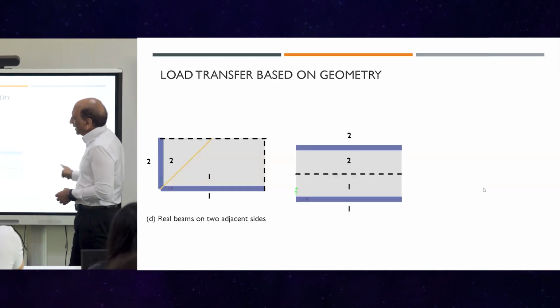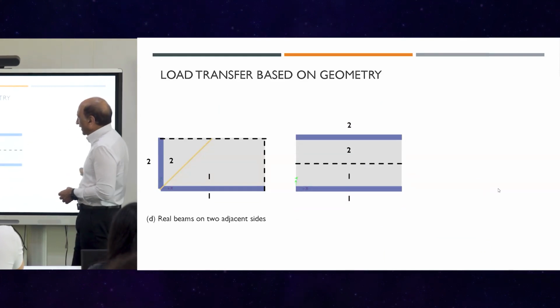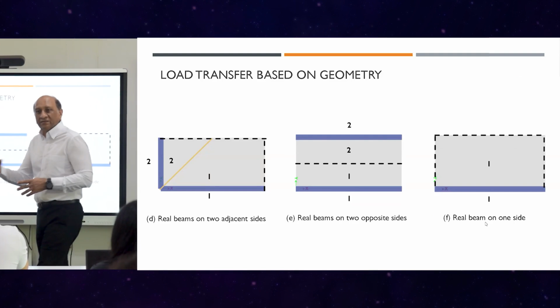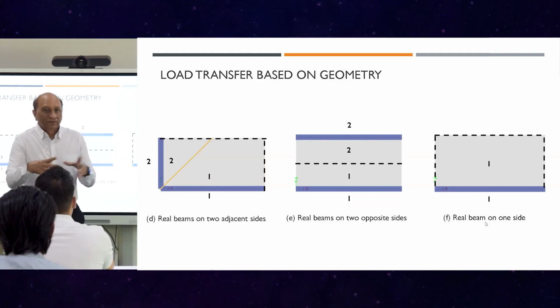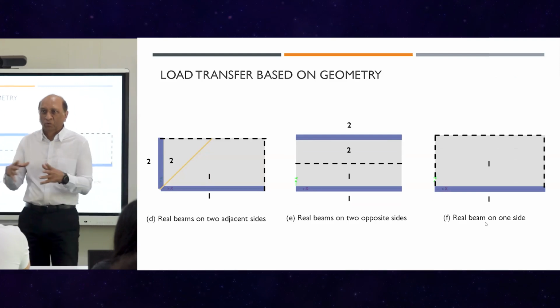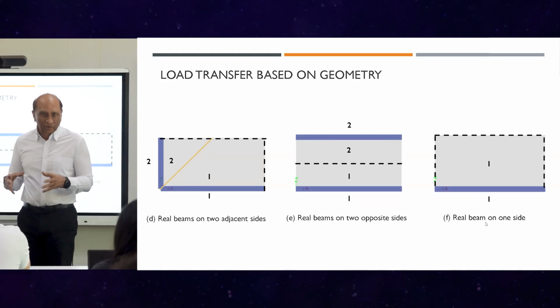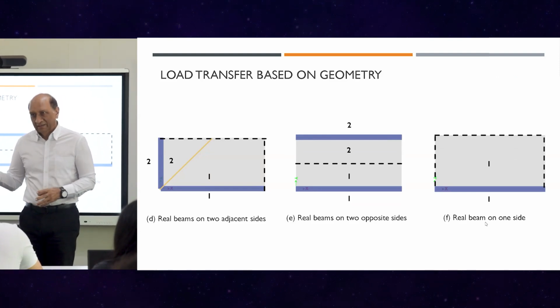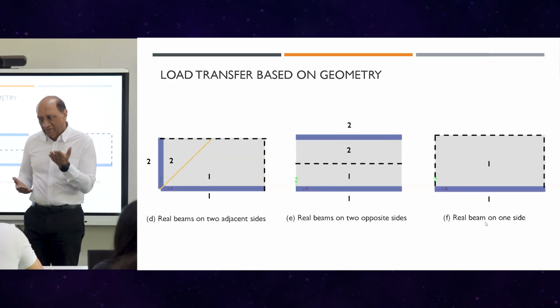So in this one, two walls will go like that, which is probably correct. And one wall, of course, cantilever will go like that. So they created all these hundreds of cases of load transfer mechanism, and it only worked for rectangular or mostly rectangular slabs. For irregular shapes, it was not easy to do those calculations. This was earlier. And so that's what CSI did.